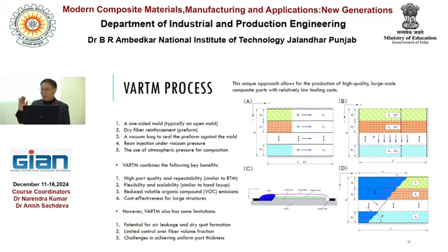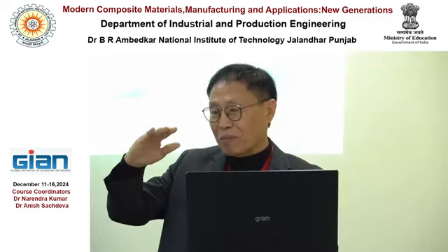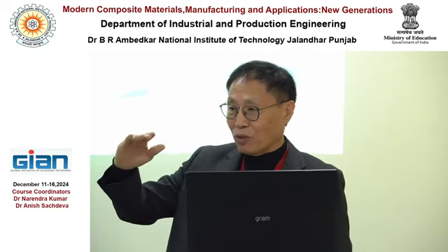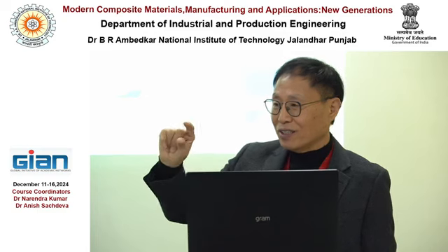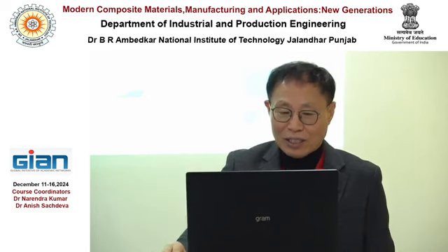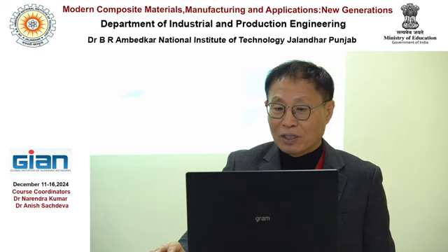And there is the challenge of achieving uniform part thickness. It means there is no upper mold. Between the upper mold and the lower mold, as in the case of RTM, that cannot be embodied here. That means the upper surface can be a little different because there is no upper mold. That means the product thickness can vary. So that is a challenging point.